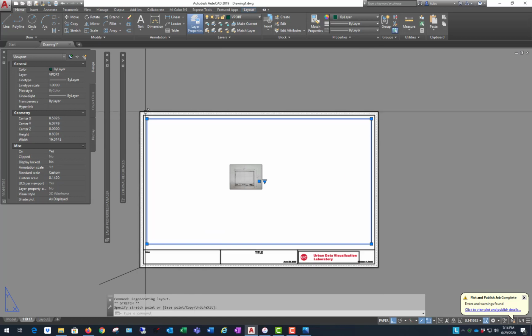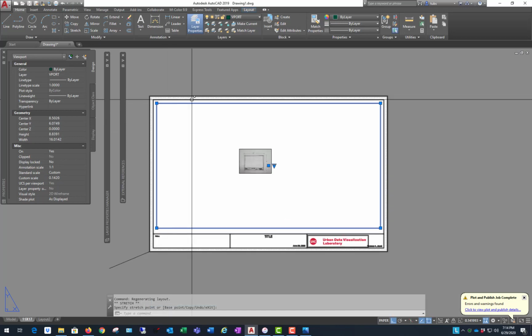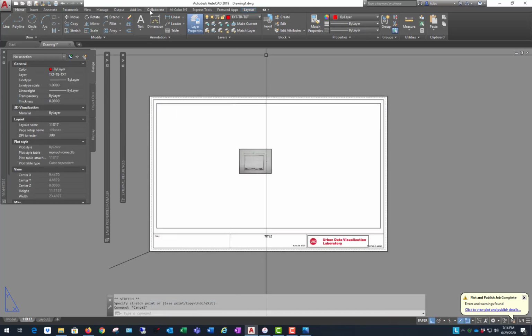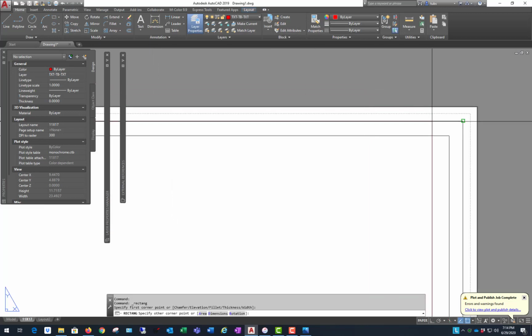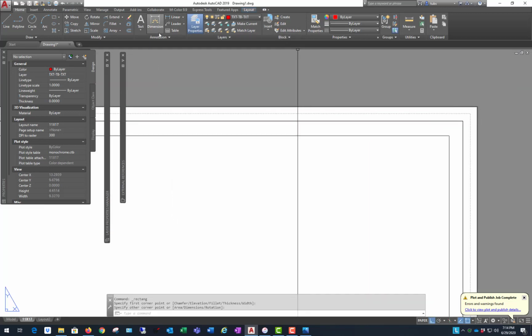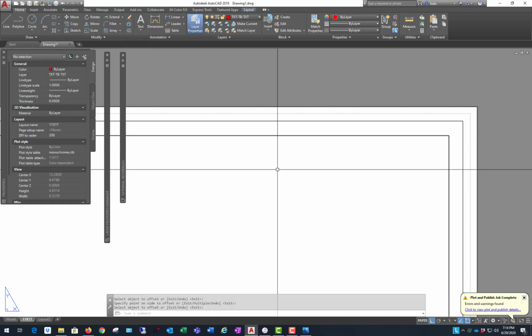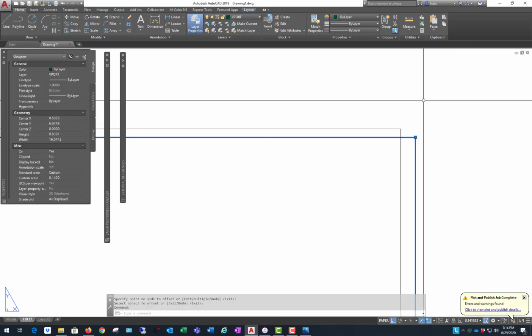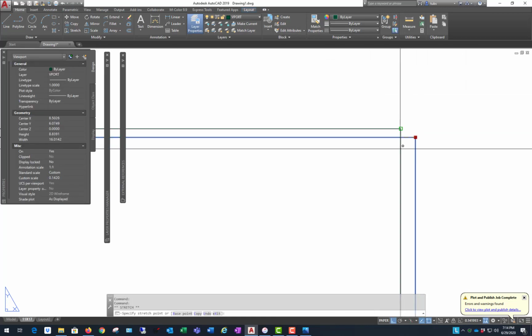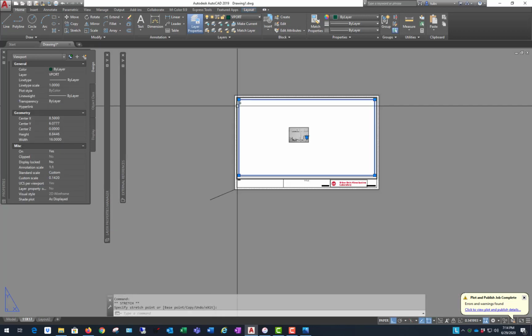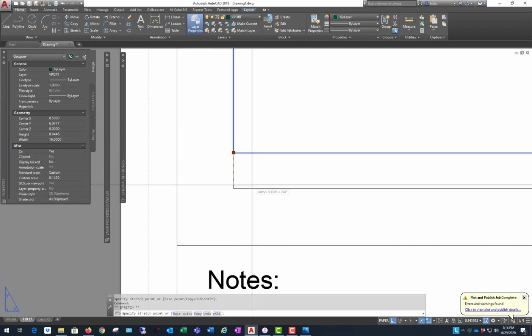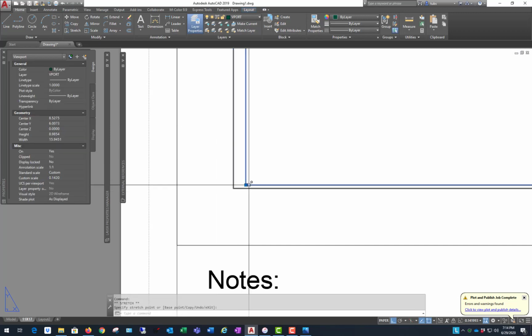And I'm eyeballing this. It's probably not the right way to go. I should have this be a distinct size, like 1/4 of an inch from the title block. So I'm going to draw a quick rectangle and offset that 1/4 of an inch. That's my viewport. I'm going to make sure it snaps to little things like this. I was close. My eye's pretty good on this, but no reason it shouldn't be perfect.